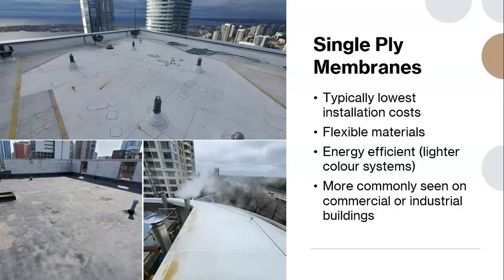Also, any areas that are experiencing heavy foot traffic or any areas that are above a residential area, not the most ideal. Areas that do experience a lot of foot traffic, there are some options to help protect the membrane. Like we can see in this photo here, there's a TPO walkway installed. So this is adhered to the membrane and is compatible with the membrane, so it would stay adhered, but it just creates a protected surface that can be walked on without the threat of causing damage to the membrane.